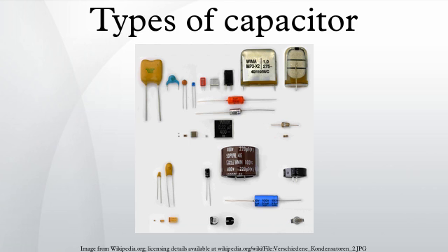Polarized capacitors have polarity markings, usually a sign on the side of the negative electrode for electrolytic capacitors, or a stripe or plus sign. See polarity marking. Also, the negative lead for leaded wet E-caps is usually shorter. Smaller capacitors use a shorthand notation.